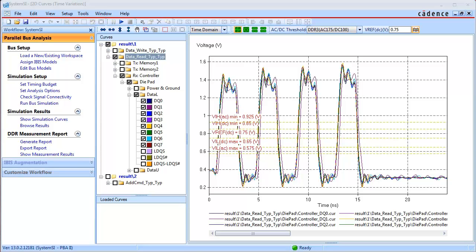With System SI, you can generate an HTML-based report file that will accumulate all the necessary simulation information into one easy-to-read report format, including simulation settings and tabularized worst-case min-max timings. However, with the new TimingDesigner interface, you can translate the results into the TimingDesigner environment for easy location of all critical measurements in an engineering-friendly timing diagram.